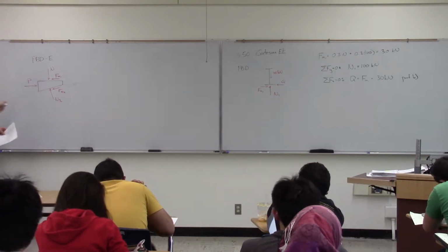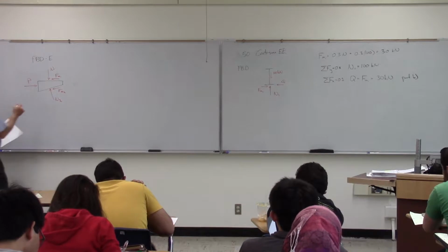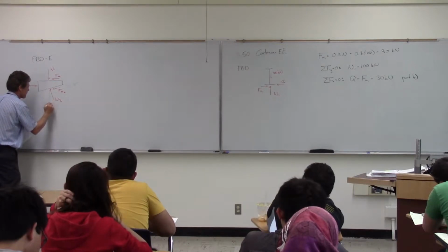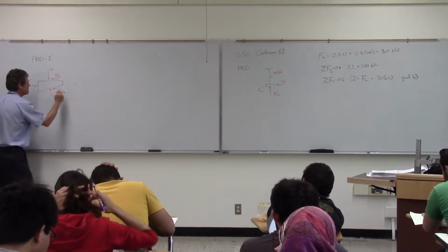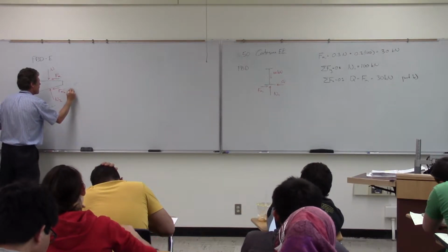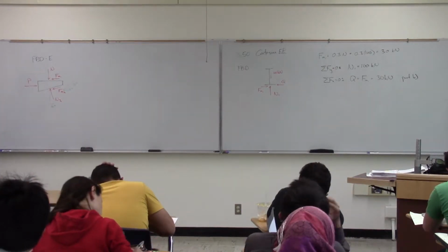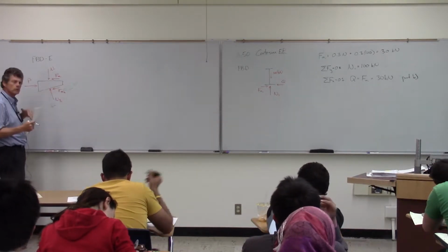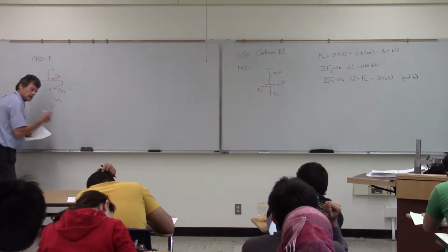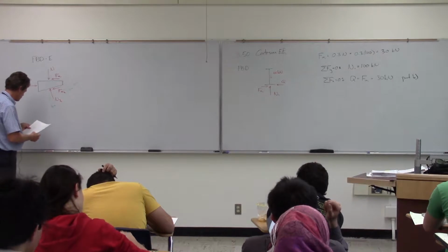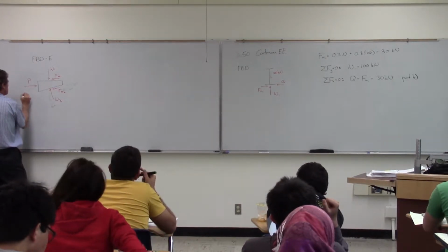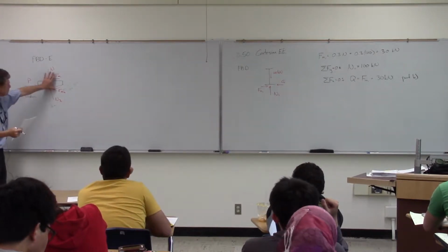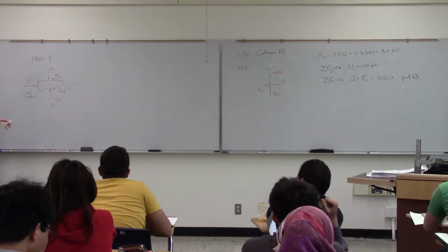And the thing that always catches people here is then we're going to have to play a little geometry, figure out the geometry here. And note that that vertical system, that perpendicular system there has just been rotated by 10 degrees in a counterclockwise fashion there, so we're just going to rotate those up. But we need to keep track of that in terms of cosines and sines. See, we got everything there. And again, our motion is this way, so it makes sense that our friction forces will be acting opposite of that.